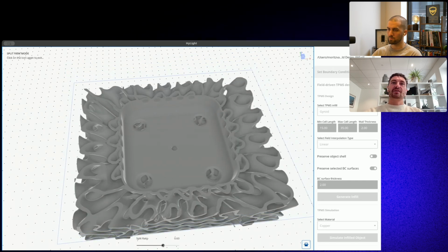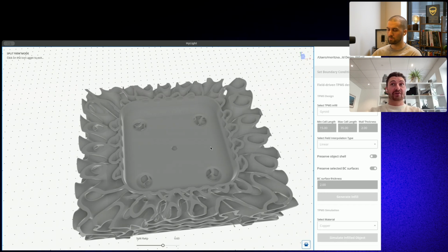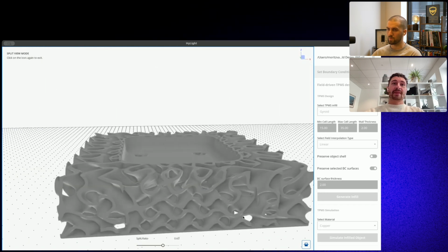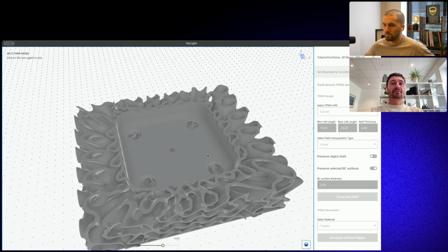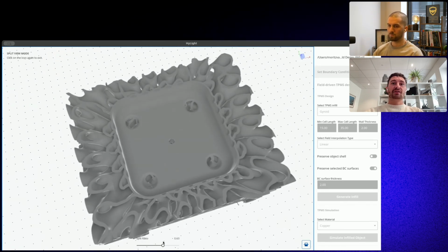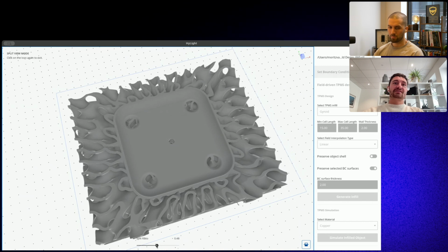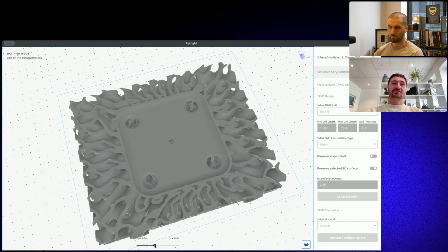material consumption. What again is very interesting, this cup is experiencing a constant heat flux of, I think I set it to 400 watts, whereas the bottom surface here has a constant temperature, a typical scenario in molding. And now you would want to conduct this heat out of the structure as effectively as possible.